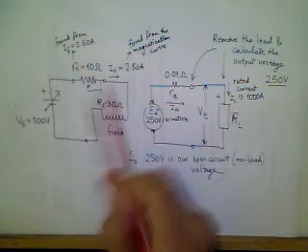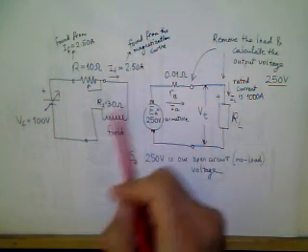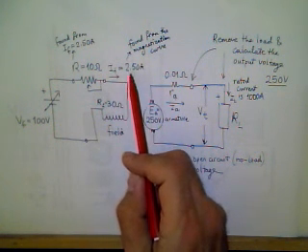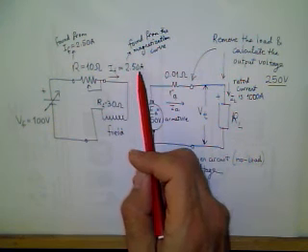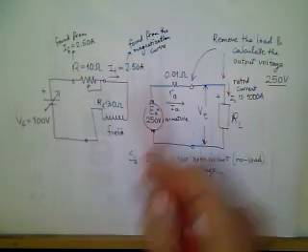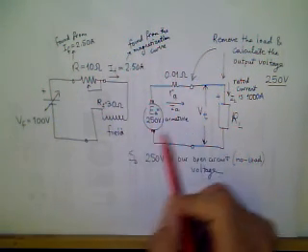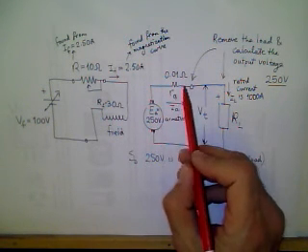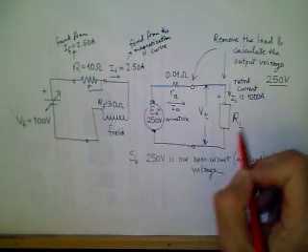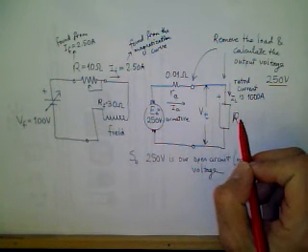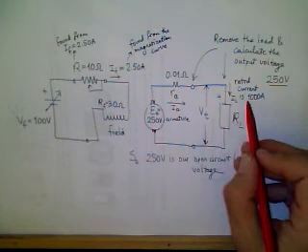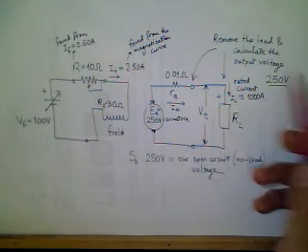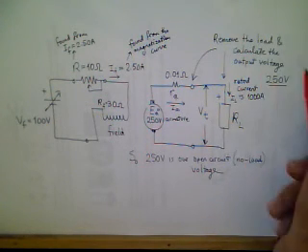Field excitation here. So total field resistance is 40 ohms. Field current is 2.5 amperes. Armature voltage is 250 volts. Voltage drop is 10 volts, and there is the load resistance. Load current is at rated, load voltage is again at rated, and load is at rated power.